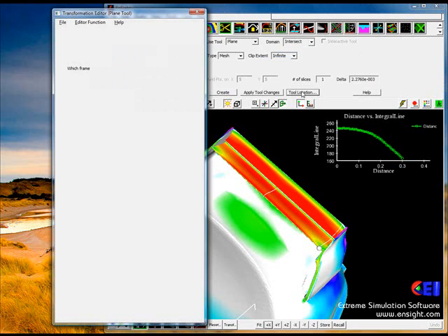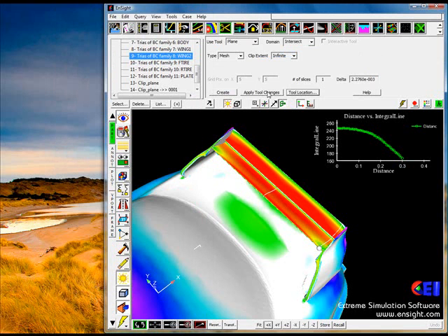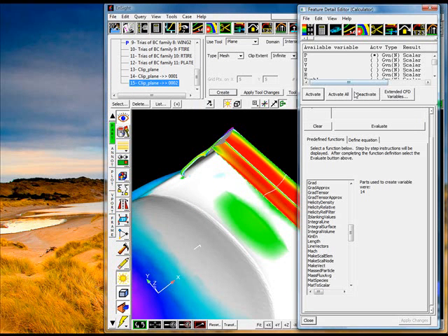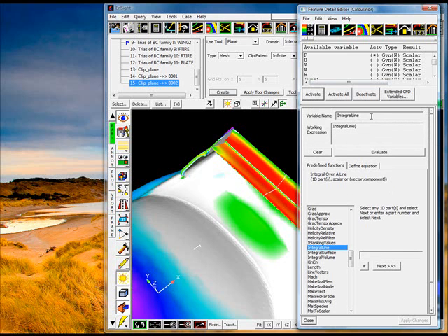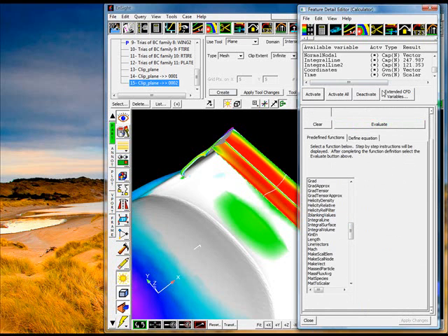So we'll do a plane to a location, -0.001. Okay, we've got another section cut here, for our second element, and we'll do the same integral again. Integral of a line, we'll call this a different variable now, integral line 2, and we'll integrate over the downforce. Okay, so now we have a new variable 121 at this particular section cut.